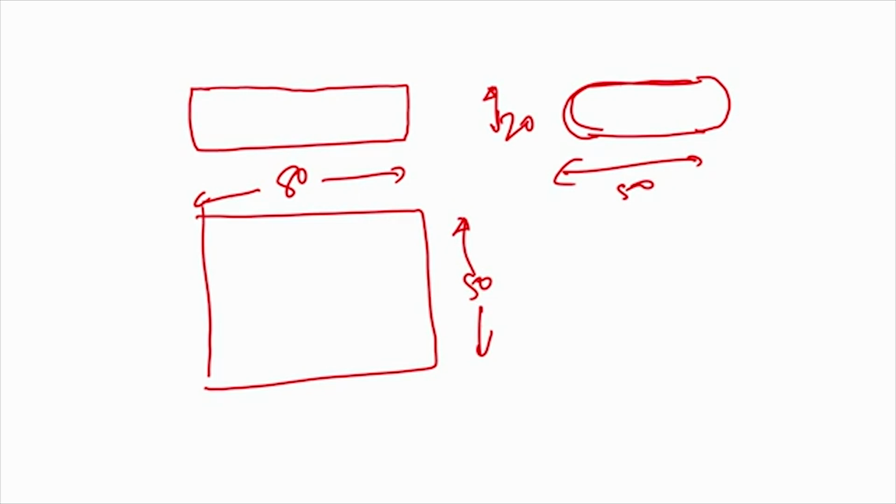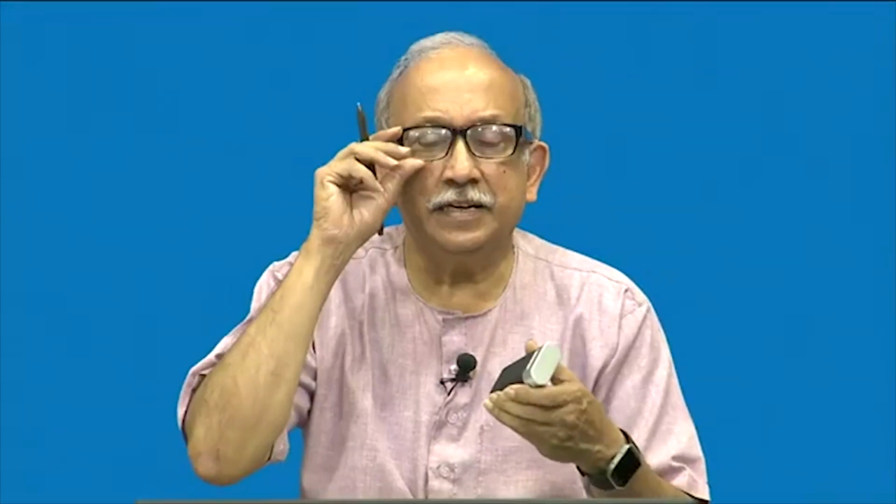Okay, generally I have got an idea, and I now add an interesting split here. Now I know that it starts looking a little like this, and then so many other things are there. Basically we have got an idea of it. Now here comes the next problem for a person who is operating a machine in a machine shop. He understands setting something is easy. Even if he has to take a solid, he will look at it, and one of the first things he will start is, I need to remove these two surfaces so that it becomes around 50 millimeters. Alternatively, he will cut both these sides to a length of 80. So we have 80, then we have 50, and then he makes everything 20. So we have a beautiful rectangular prismatic object.